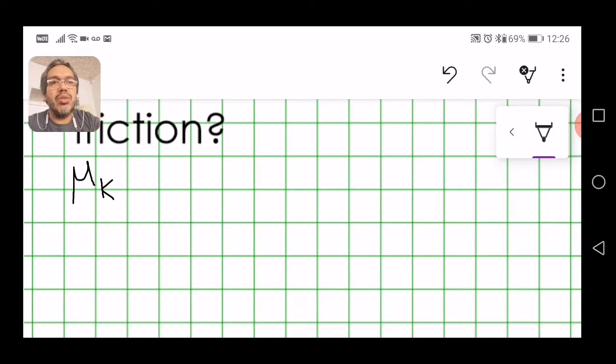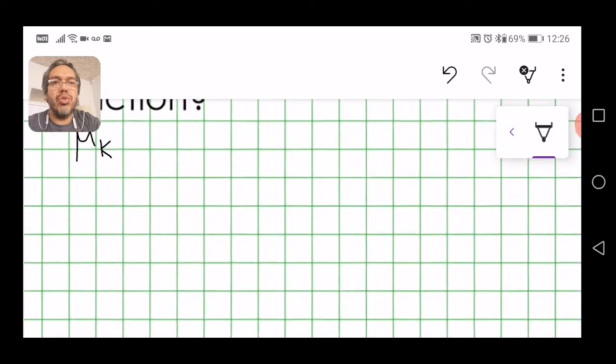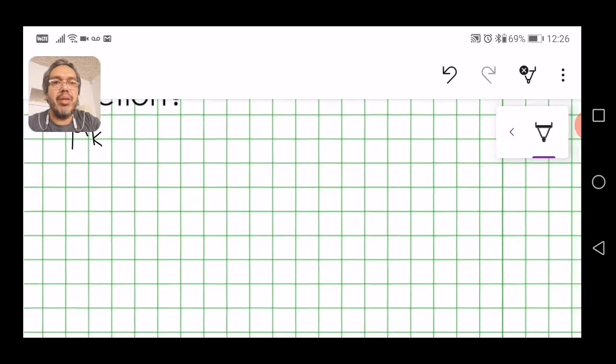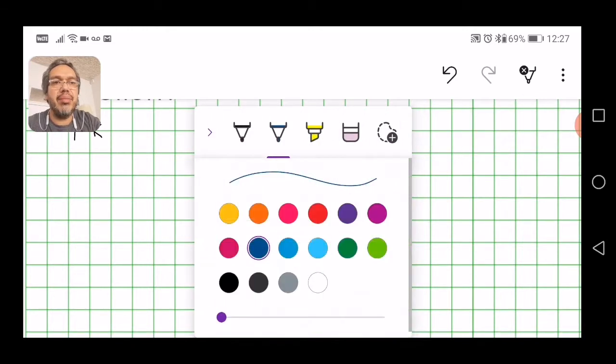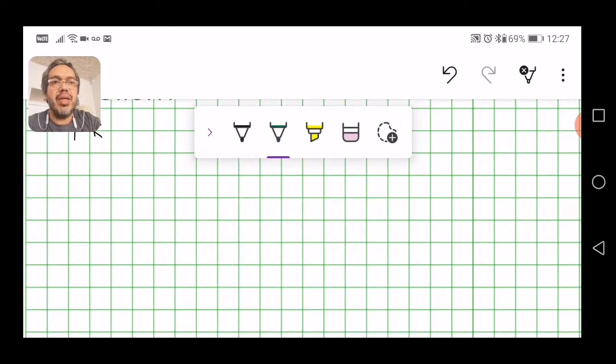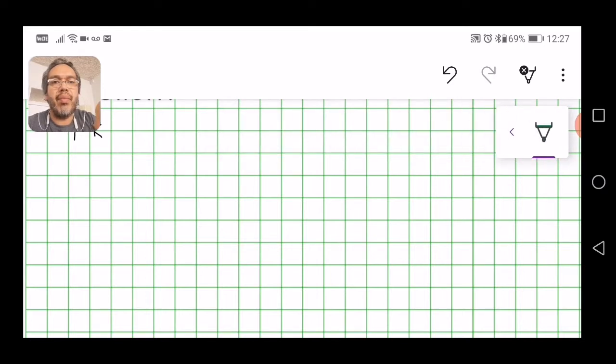Now, in order to do that, of course, you need to do a problem with forces, which means that you definitely need a free body diagram, and that free body diagram needs to be rotated. Now they tell you that the angle of the inclined plane is 40 degrees, therefore your x-axis is 40 degrees with the horizontal, the y-axis is 40 degrees with the vertical.